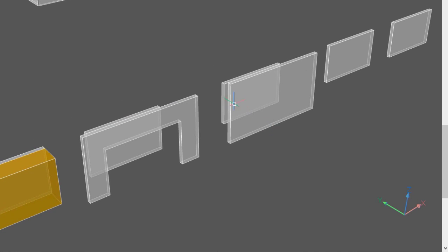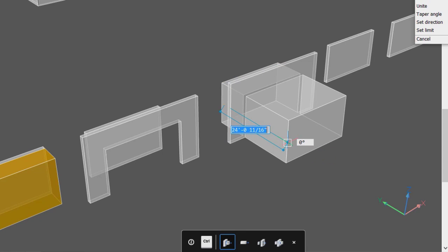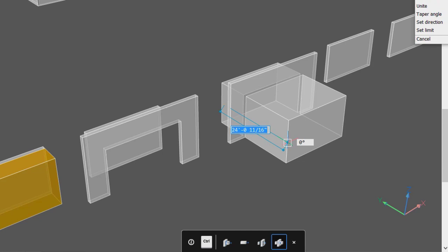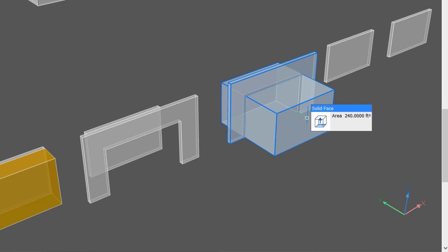For the fourth option, we'll also need two walls. We'll go through the same selection process and hit Ctrl a third time. And specify a distance. The result this time is a solid passing through the second wall versus creating a void. In addition, the overall geometry of the extruded wall and the second wall are now one object.